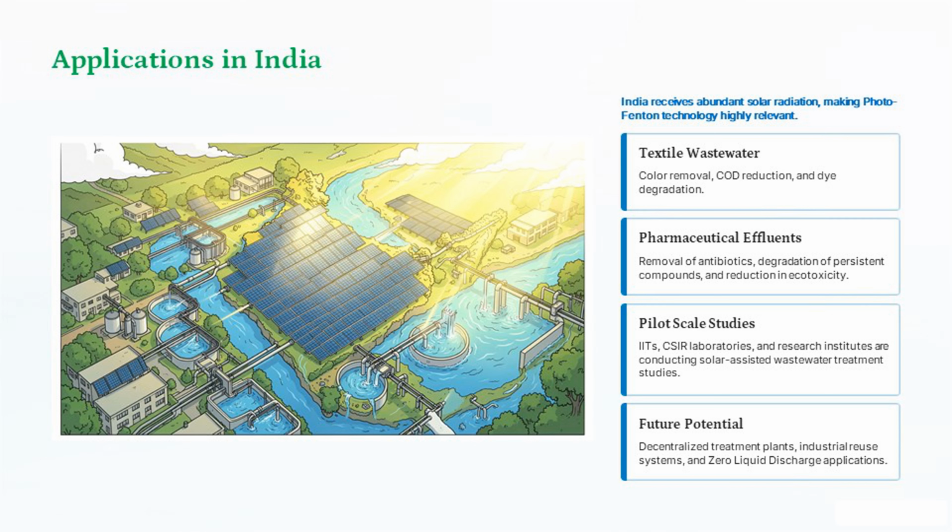Now, the applications in India. India receives abundant sunlight for most of the year. This makes Photo-Fenton technology particularly attractive for Indian conditions. One major application is textile wastewater treatment. The process effectively removes dyes, reduces color, and lowers chemical oxygen demand. Another important application is pharmaceutical wastewater treatment.